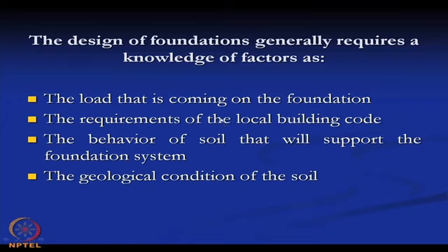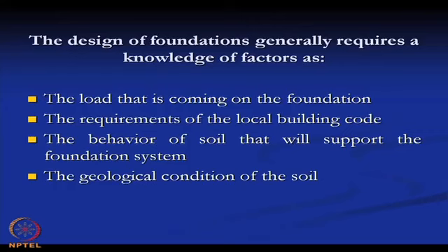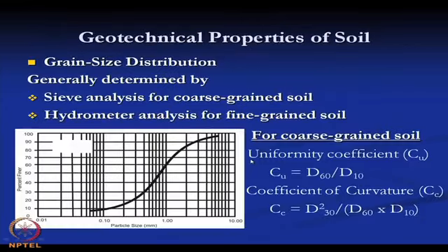Then we need the required design codes and building codes of the area where we are designing the foundation, and the behavior of the soil that will support the foundation system, that is, the soil properties. We should know the soil properties before we start the foundation design. To know those soil properties, we have to go for soil exploration, with laboratory as well as field testing. And then the geological condition of the soil is also required.